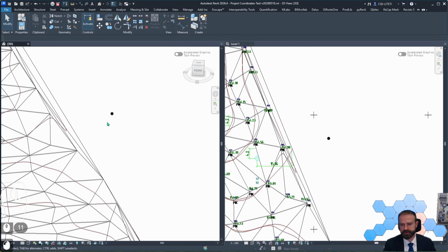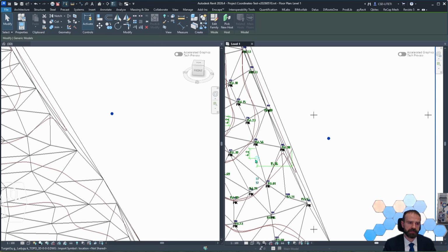And here I have this point representing my point on the map. To move this point, I cannot write coordinates by default using Revit tools, so I just need to use the move tool or set specific dimensions and move it to the needed position.